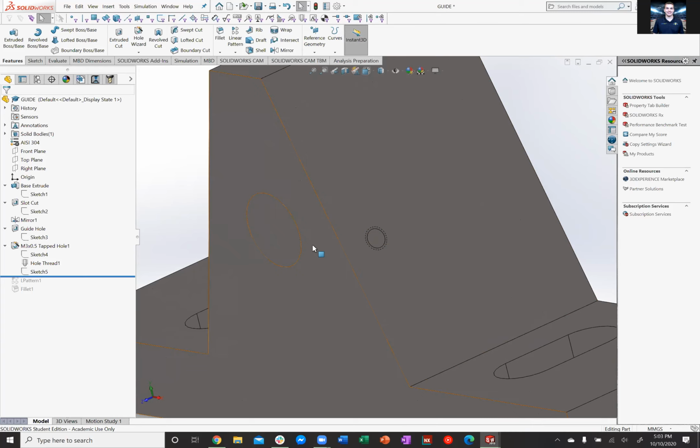You can also do combination holes, I think. You can add a countersink on here if you want. And if you don't want to go through the whole hole wizard process, you can do a chamfer, but it's good to go the official way with hole wizard for any tapped hole. And then, you don't have to make all of them. You can just make one hole.